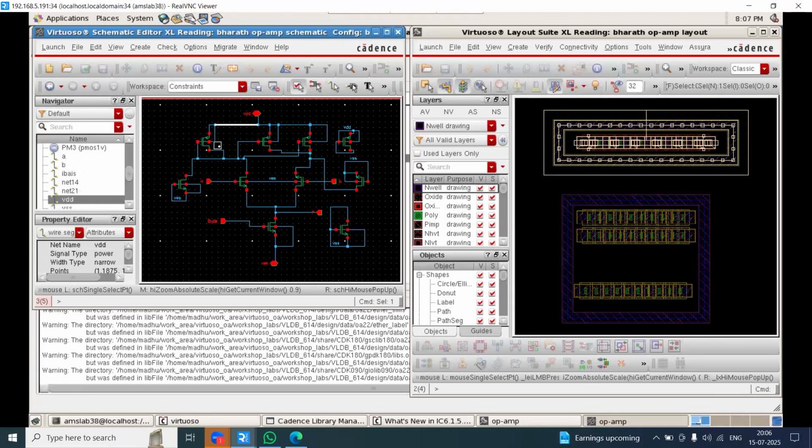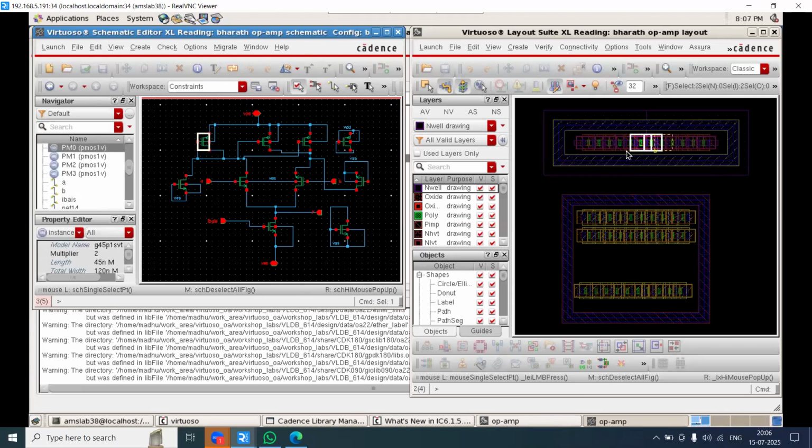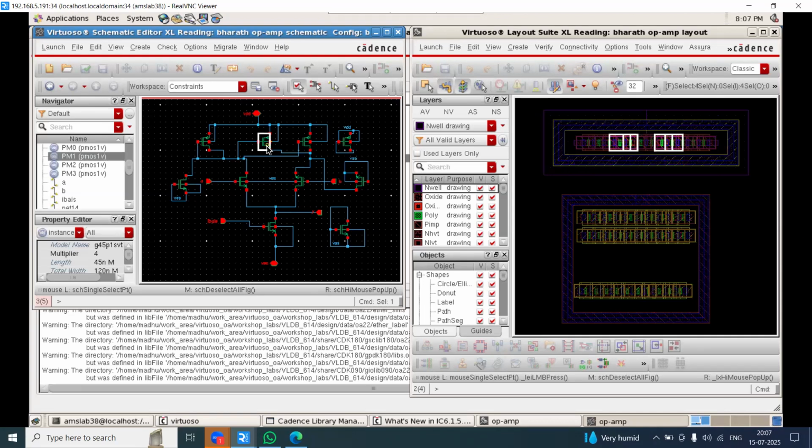Getting, ma? Clear? So in order to make that, I have placed a diode connected device in the center, and on 2 sides I am flipping, meaning I am splitting 2 devices on one side, 2 devices on the other side. Interdigitized, ma. Okay.